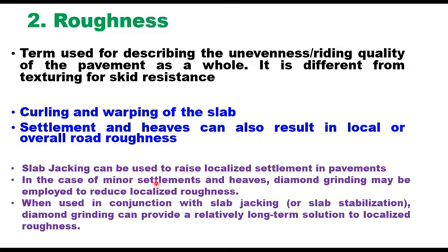In the case of minor settlement and heaves, diamond grinding can be employed to reduce localized roughness. But when you use the combination of these two, slab jacking as well as diamond grinding, that can provide a relatively long-term solution to localized roughness.